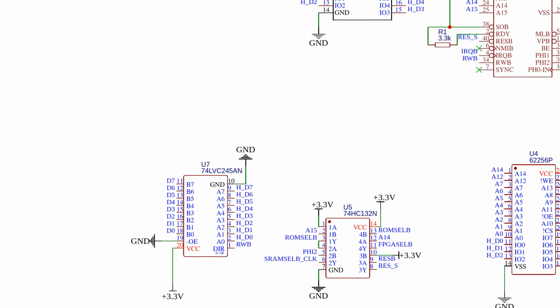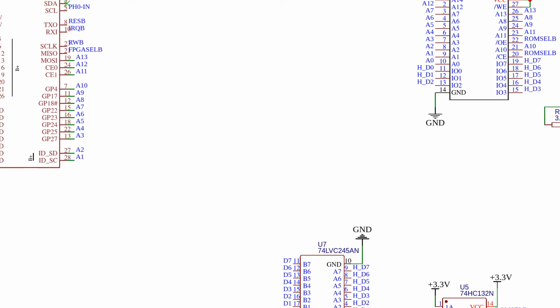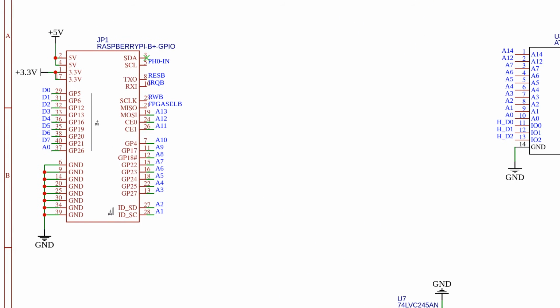I also considered moving all of the address decoding to the FPGA, but in order to do that, I would have to send all of the control signals to the RAM and ROM from the FPGA, and I simply did not have the pins. So I went with the simplest decoding I could think of, using only a single NAND gate chip.